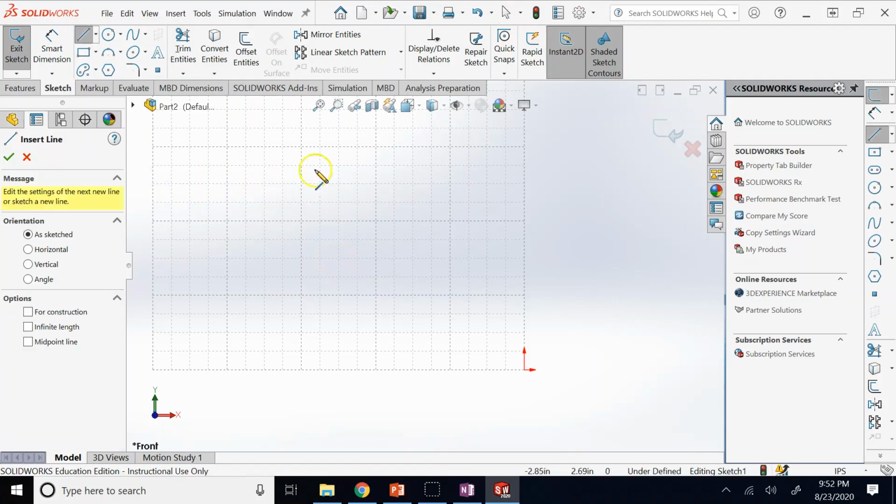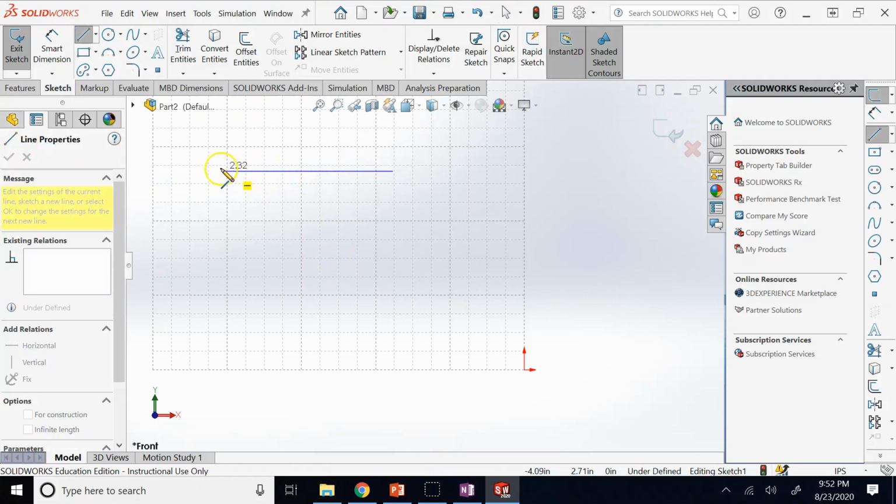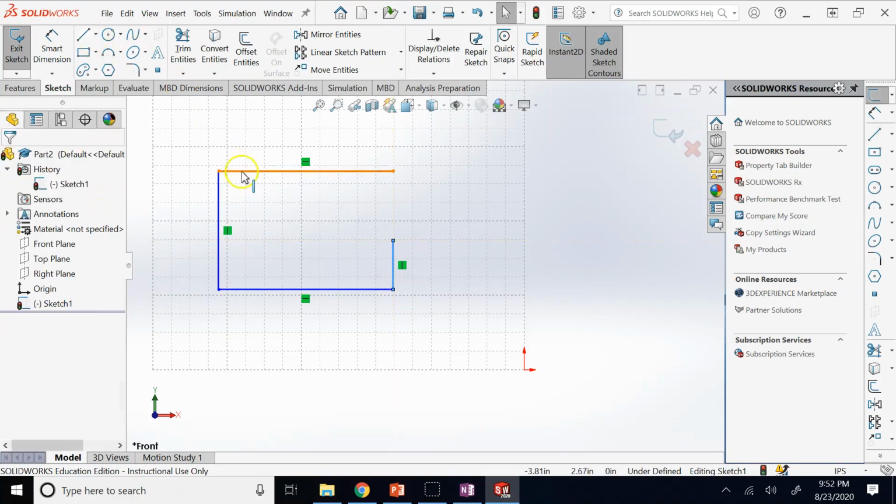Another thing which, although you do not really need to use it, could sometimes be a little bit useful, is the command extend. So here, let's say I want to extend this and bring it all the way to the other line and make these 2 points on top of each other, coincident basically. So how do I do that?